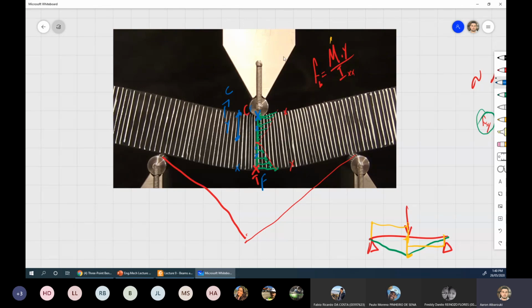But all what we're saying, I can calculate the stress, the flexural stress in a beam at any point within that beam. First of all, to start with, at any section, I can calculate here, there, and there, and there. Wherever you choose that section, all what you have to do, use the value of M for that section. Let's call it M1, M2, M3, M4, M5. Doesn't matter what you choose, because each one of those has it. Look at it. M1 here, 2, 3, 4, wherever. Each one of those will have.